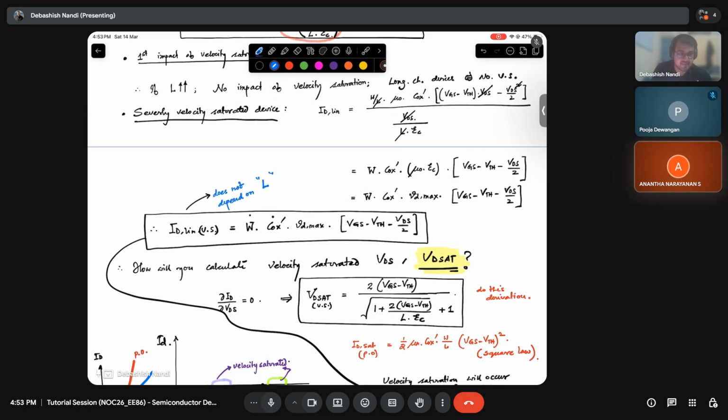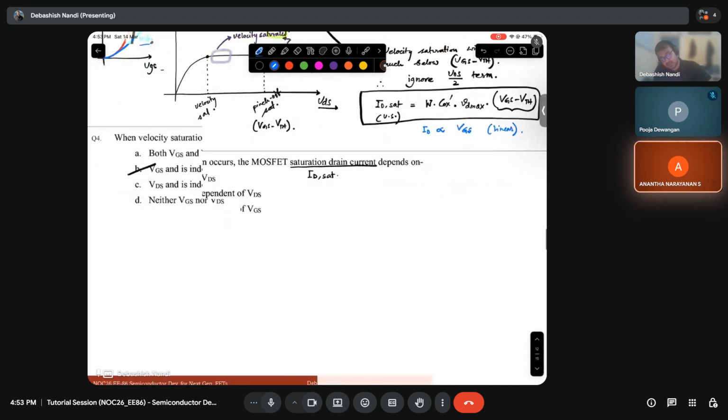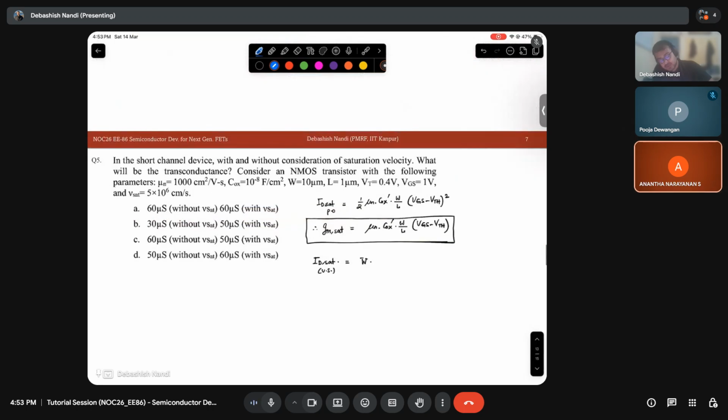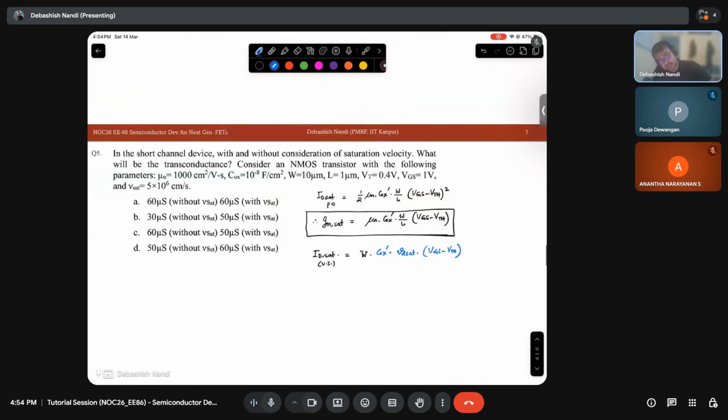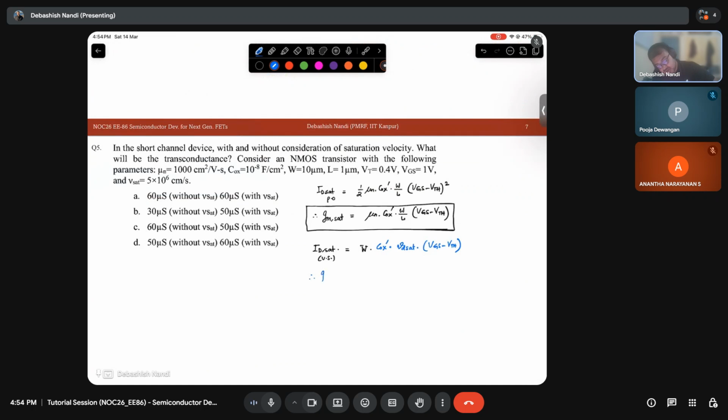Yes, sir. So this is W times Cox times VD sat times VGS minus VTH, if I am correct, yes. So your GM sat will be W times Cox times VD sat.